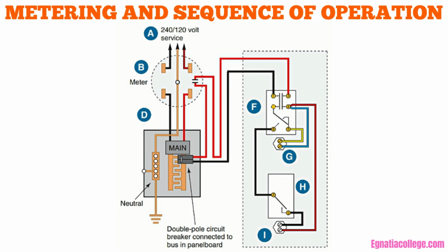Connect the water heater to one of the two-pole, 240-volt circuits in the main distribution panel. This is probably the most common method because the wiring is simple and additional switches, breakers, time clocks, or meters are not required. This is the connection for the residence used as an example in this textbook. This method provides electricity to the water heater 24 hours of every day.